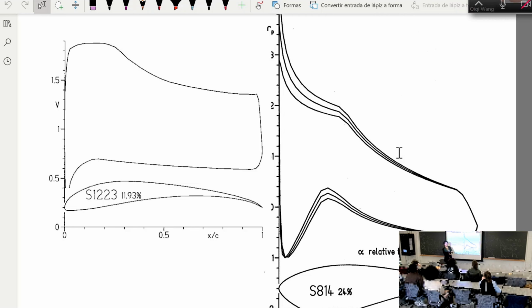The viscous force is less strong when the boundary layer is thick. And viscous forces help make the boundary layer more equal, right? Make it closer to a Blasius boundary layer. While the adverse pressure gradient tries to make the flow separate, it magnifies the velocity differences between the different layers, as you have worked out in class.